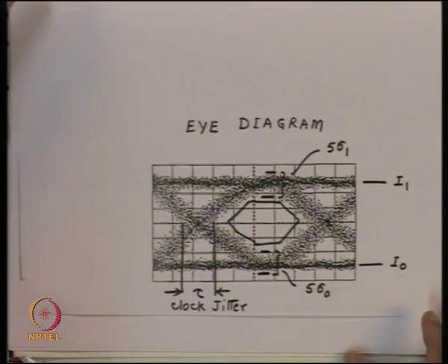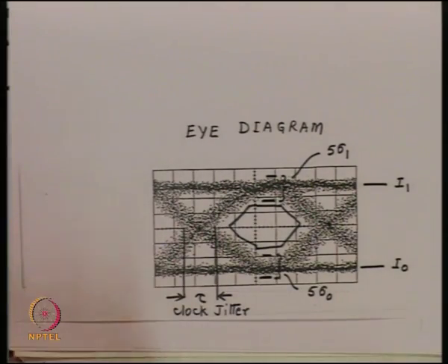And when any of these situations happen inside a receiver, you have performance deterioration. So, the eye diagram is one of the very important diagrams. After the system is designed completely and commissioned, one has to perform the final test on the data, which is what is called the eye diagram, and then only one can satisfactorily say that the optical receiver is performing satisfactorily. So, these are certain tests which are conducted on the optical receiver, and the parameters are extracted to calculate the quantitative parameter, what is called the bit error rate.